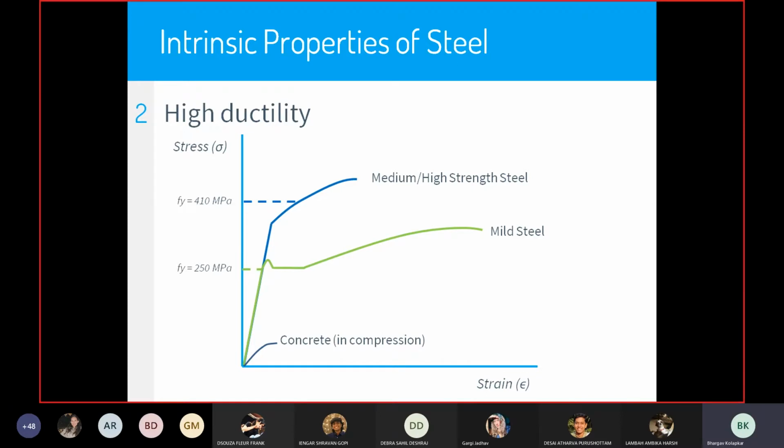I'm talking about the structural system only, the main lateral load resisting system and nothing else. So my beams have to be ductile. My column, if you are designing it for special detailing, then every element of it needs to be detailed in such a way that it is ductile. Did I answer your question? Yes, yes. I had another one, but this answers that as well.